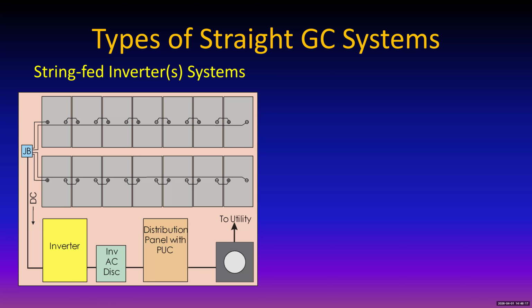And then that's going to do some things to mess up its output, because if it's shaded, it can't put out the same amount of power the other ones can, and yet they all have to put out the same current. So that's why that's called balancing the system. You need to make sure that these things are set up so that every module will perform, and in this particular case, put out the same current because they're in series.